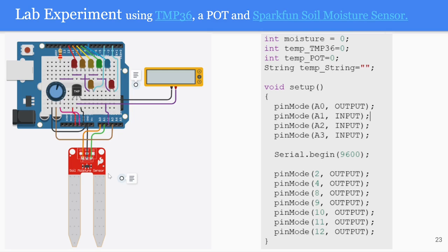So this is the soil moisture sensor. It will detect the moisture in the soil. This is a TMP36 sensor, which basically is kind of a thermistor, which we will use to measure the temperature, and it's connected, as you can see here. So this is its analog A2 line. There it is coming in, and this is simply the power and the ground connections.